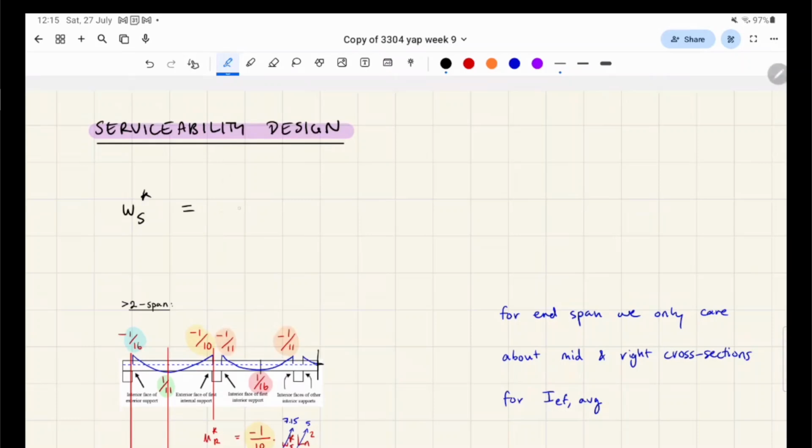No, all good. So basically, for strength, we have these ones. Oh, 1.35G and 1.2Q, yeah. But we actually don't use those for serviceability, because serviceability is about deflections. It's about everyday loading rather than worst case scenario loading. Serviceability is about making sure that over time the slab doesn't deform too much. It doesn't warp out of place, basically.